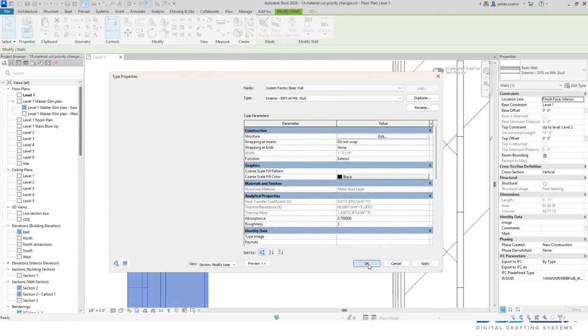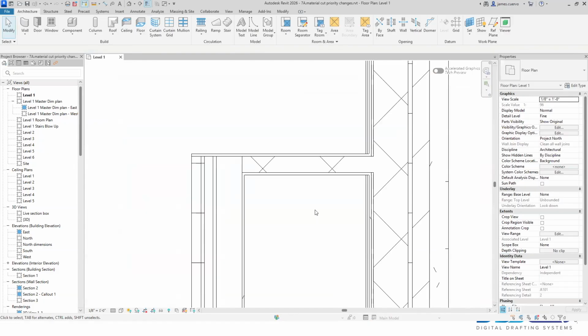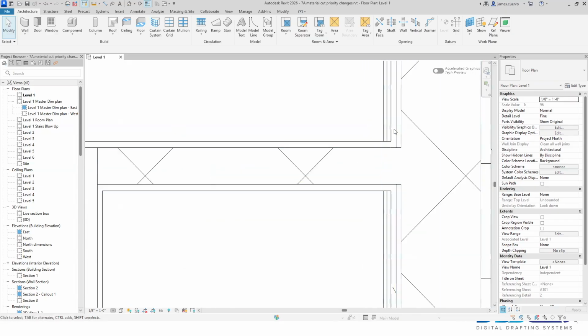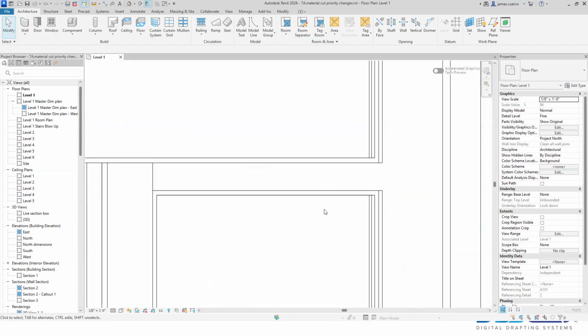So with that, we see that, yes, it goes ahead and it merges, everything is perfect, but you need to be careful, because for some reason, I actually do see the logic. The material on that particular object that you define to be equal to the other object's priority cut, the material is different. The cut might be the same, but the material is different. Therefore, it creates a line for you. There is no unification of actual faces as it is with this chipboard here and this chipboard there, right?